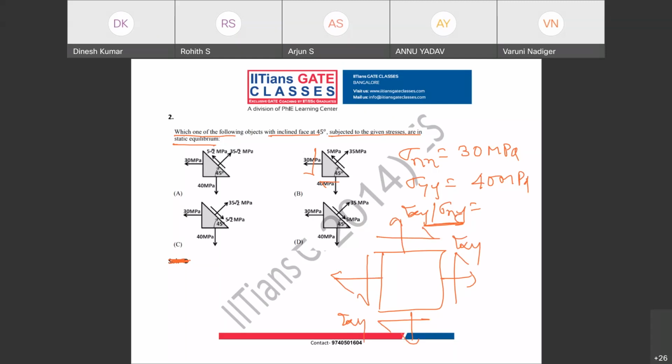Now can you tell what is the tau xy or sigma xy in this case, guys? If you see all four elements, you don't see any shear. So what is your shear stress? 0. Exactly, it is 0. If you take the xy direction, your shear stress is 0. So this is given. Now what is asked? What is your sigma s and what is your tau st? Because they took this plane, right? So this is sigma s and this is tau st, right?